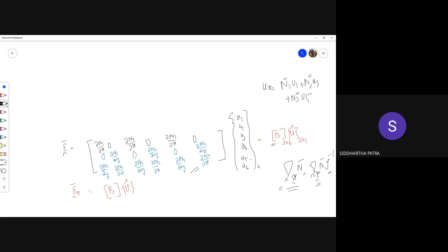Of course, the displacement of each node would change, but constant is a loosely used term here. It basically means not a function of xi and eta, that is, not changing inside the element. These are nodal degrees of freedom, so they are also not changing inside the element. So what I get here is that this strain vector is not changing inside the element. It is constant within a given element. The strain would be constant within a given element.